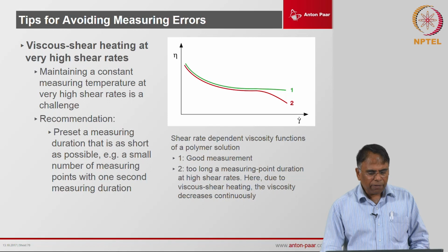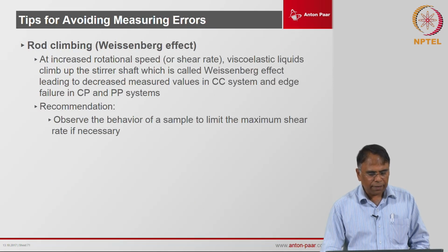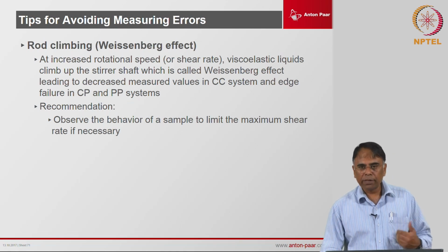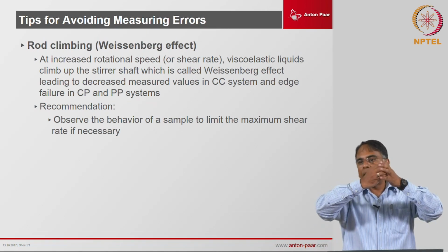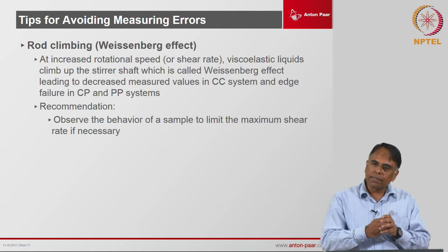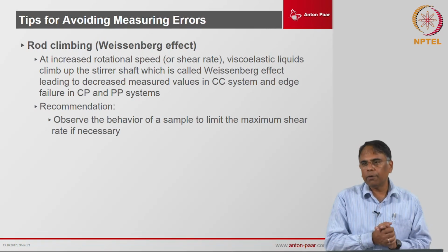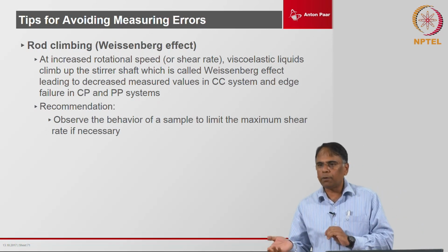So, other simple effects: viscous shear heating effects at very high shear rate, and the Weissenberg effect. If you are using a coaxial cylinder system, you can see sometimes the sample climbing up the rod of this coaxial cylinder system. Okay, it can happen only in a coaxial cylinder system, not a parallel plate and conal plate.